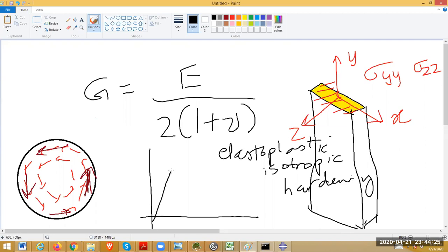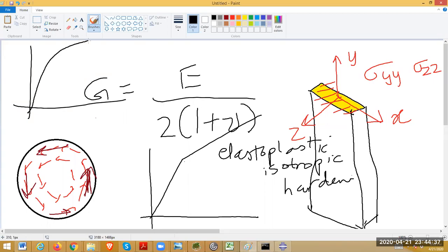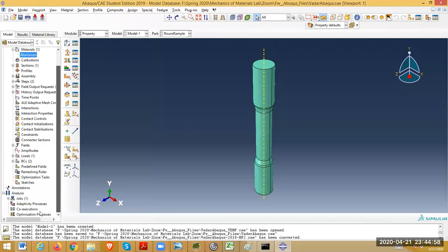That means the uniaxial stress strain graph goes like that. Okay, this is the yield point. Of course, the actual material goes, but we model it as a sharp point there. That is much easier to model. So that's why we give this point and another point, so that Abaqus can interpolate and form this line. Okay. So once we give that, what extra thing do we get?